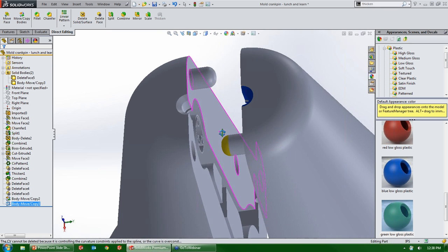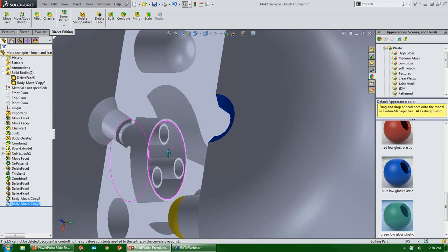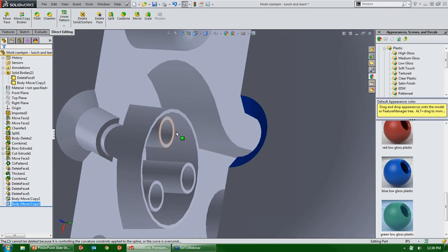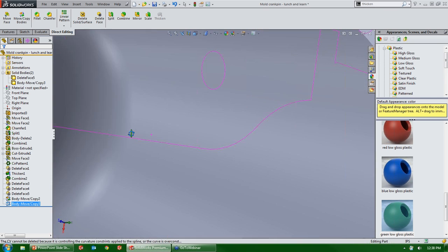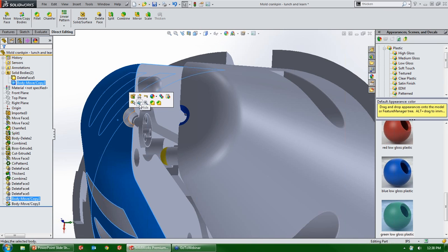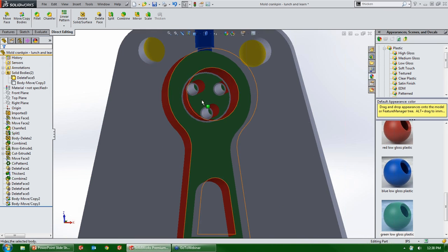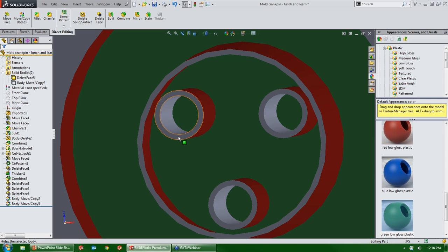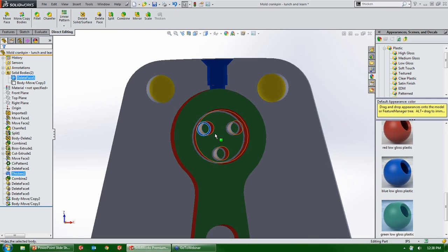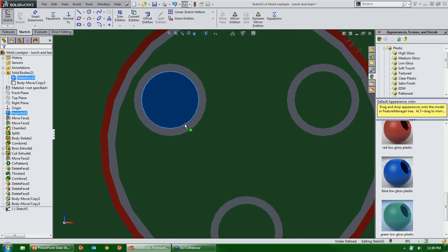All right. The last thing I think we need to do is create a male side to this. So we'll call this our female side, and we'll keep working on our colorful one over here. So we know this is lined up. I'm going to hide it. We'll come back to it in a bit. The last thing I need to do is create a couple connection points on this. So I'm going to take this surface, make a new sketch, and then convert a couple entities.